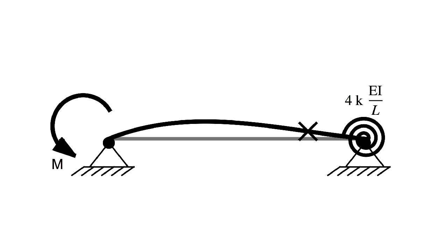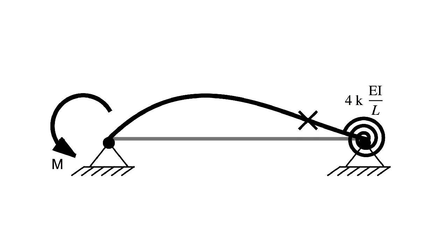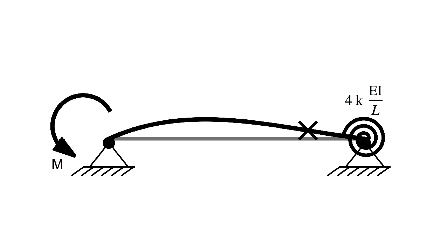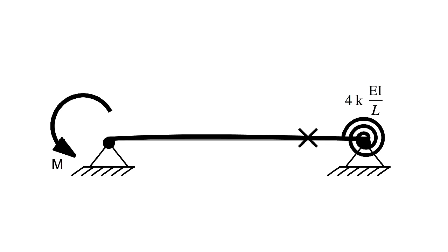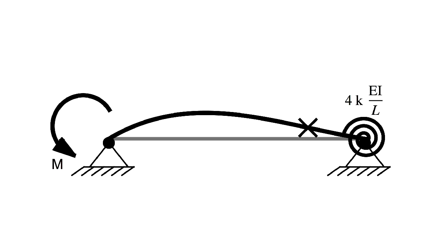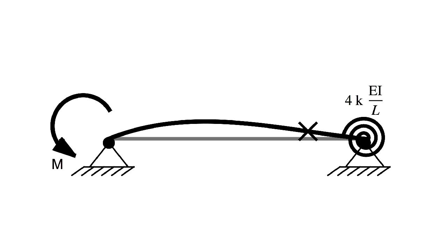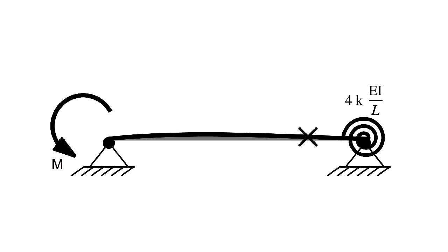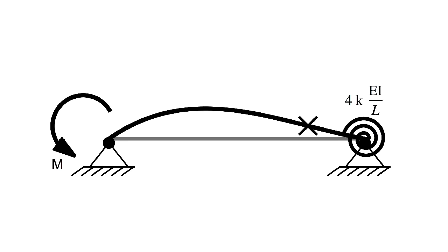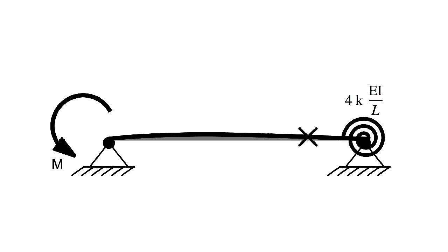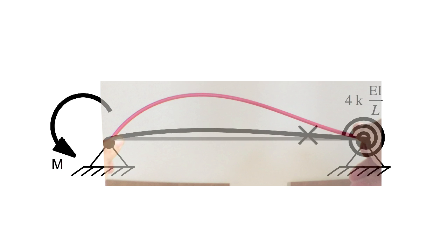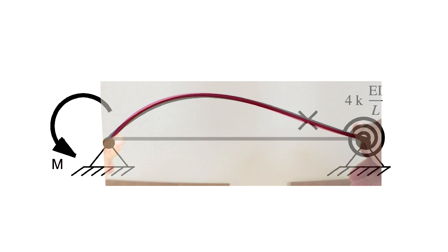So now we see the deformation of a hinge rotational spring beam. Notice that, typically, it's closer to the freely rotating hinge case than it is to the fixed end case. There's a slight positive curvature visible near the spring, which becomes very clear only at unusually large stiffness factors that are not typically encountered. Now, we compare the deformation of a straw with this case, and we get a match.